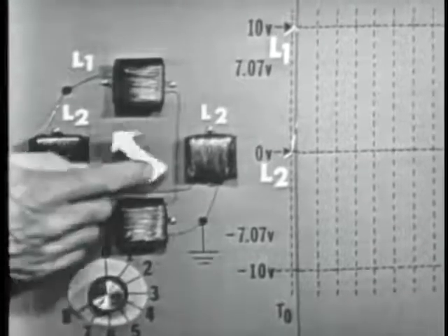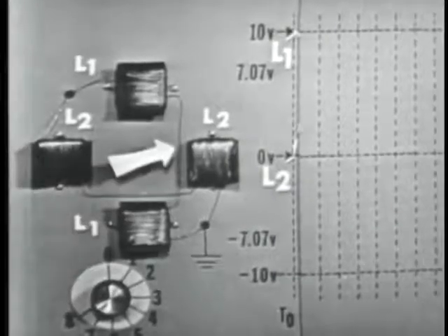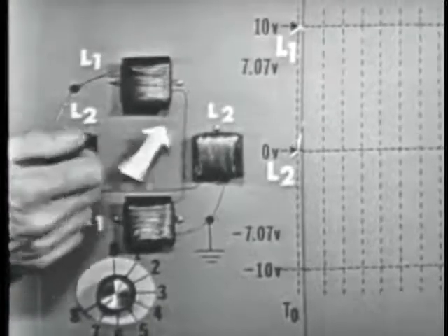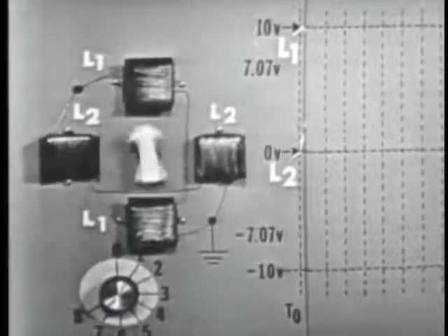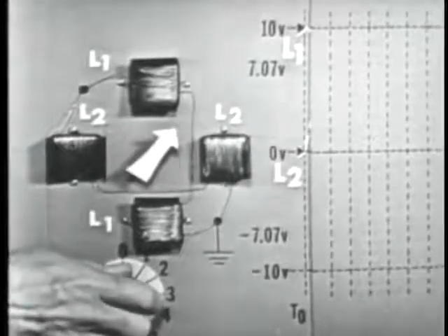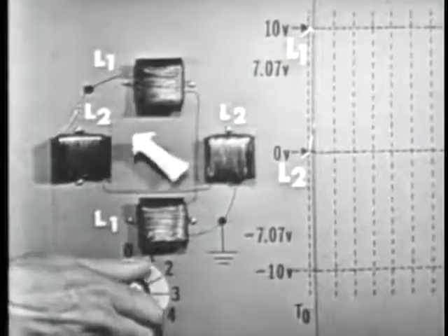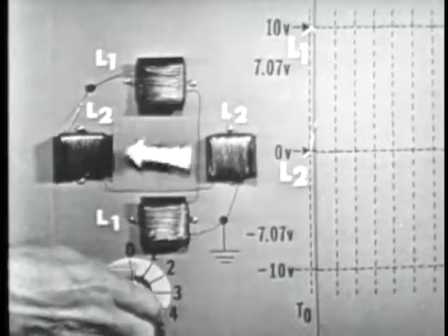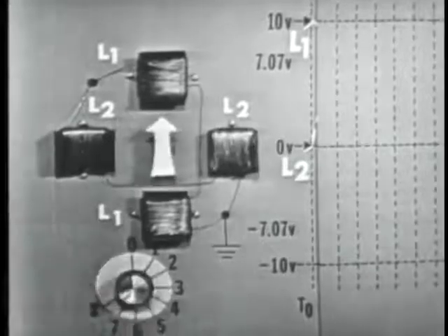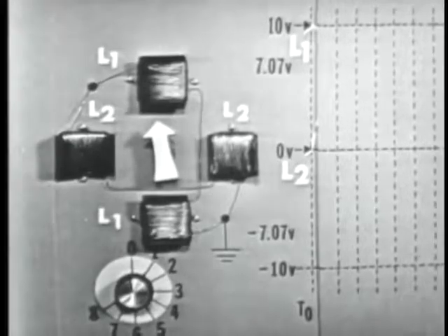Now, in the center of the coils, we've placed a permanent magnet with an arrow on it to show the direction of the magnetic field at any one time. Now, this permanent magnet is simply glued to a ball bearing so that it can rotate freely. Now, the object of this demonstration is to cause this arrow, this magnet, to rotate 360 degrees by causing the magnetic field produced by these coils to rotate 360 degrees. So that you can understand exactly why this happens, let's take a look at the way these coils are wound and how the voltages will be applied.